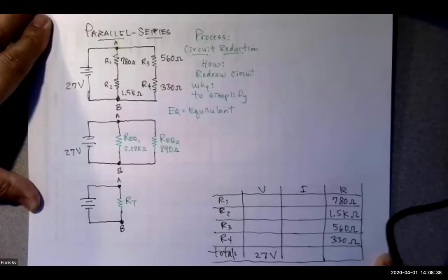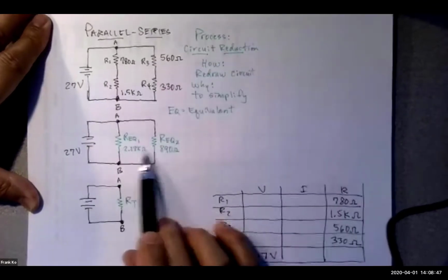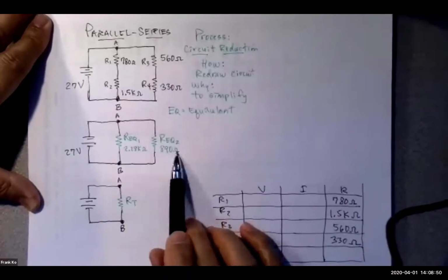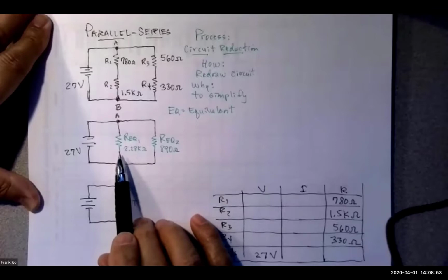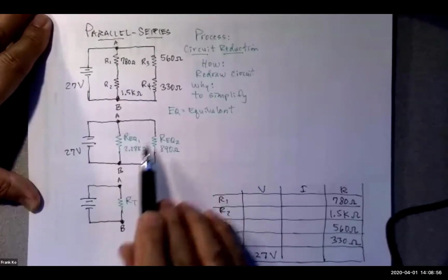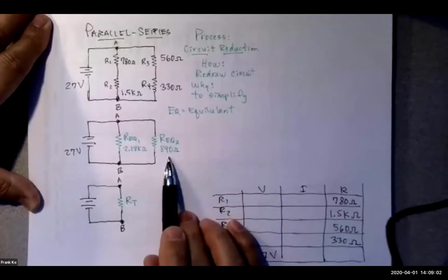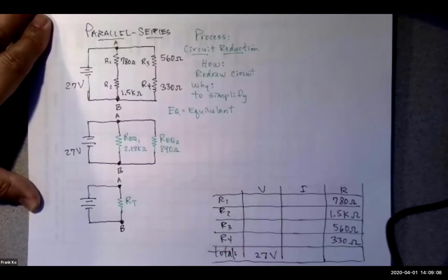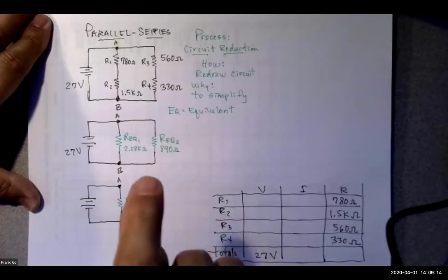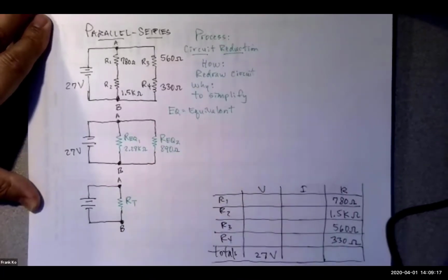Precisely. That's the verbiage that I'm hoping each of you have emblazoned to the back of your retinas. The total resistance of any bank of resistors, remember the nickname for parallel circuits is banks. This is one branch, this is a separate branch. And the total for these must always be less than the lowest ohmic branch. So it's got to be less than the 890. That's the verbiage that I want you to instill in your hearts, to be able to just say, boom, I don't know anything about the actual number, but I do know it's got to be less than 890. So if you calculate something more than 890, boom, there's something wrong in your calculations.